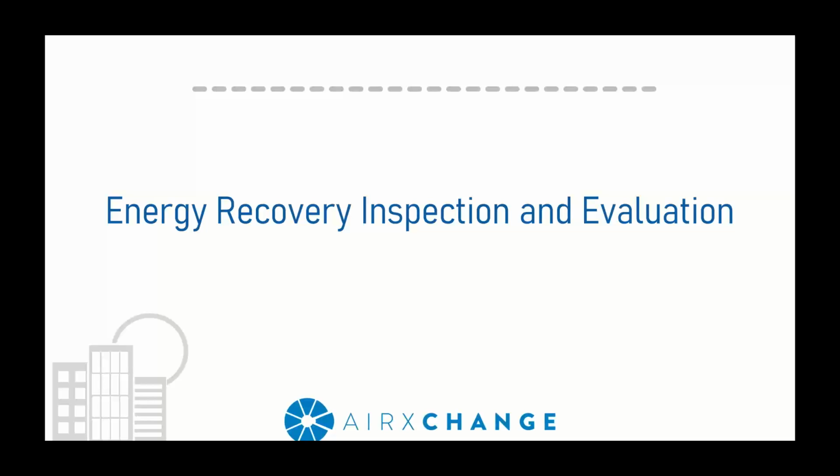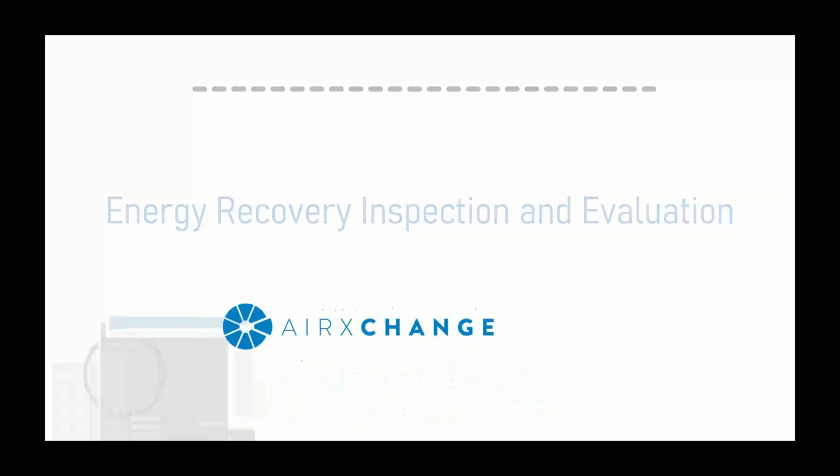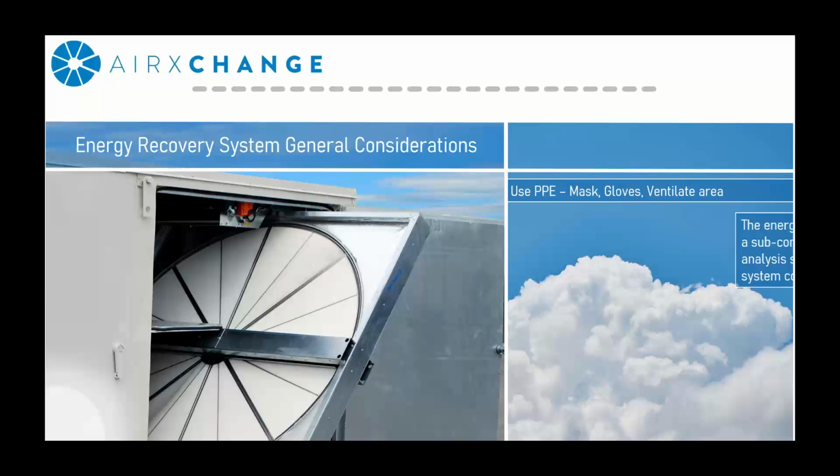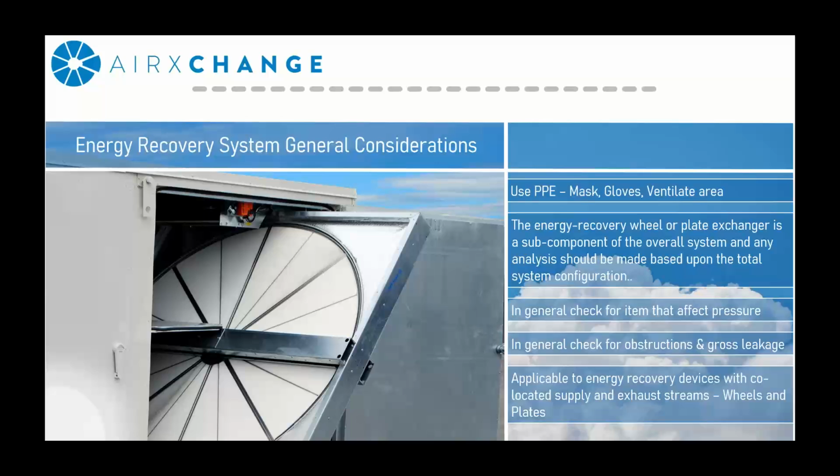Okay, so the next section is going to cover how to inspect and evaluate an existing energy recovery system so you can determine if the system is well designed and well maintained. So the guidance that I'm going to share here is based on the TC55 practical guidance document, which is the operation of energy recovery devices document that I spoke about earlier. It is available on the ASHRAE website, and it's really intended for building operators to use in their bag of tricks as a means to inspect and validate.